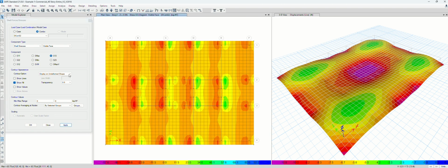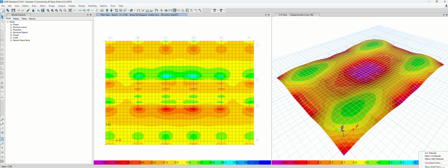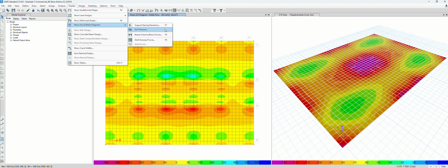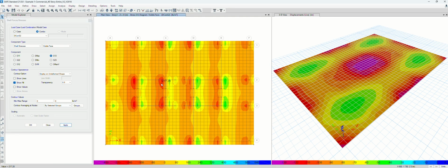So it's showing some vertical shear stress, 1-3, 2-3. Since the numbers shown range, oh, these are kips. So let me change to PSI unit. So here I'm going to use PSI. Again, shell stress. Turn on that, ultimate, 1-3. So here, minus 217, right? So maybe I can put that, is it 212 or 221?